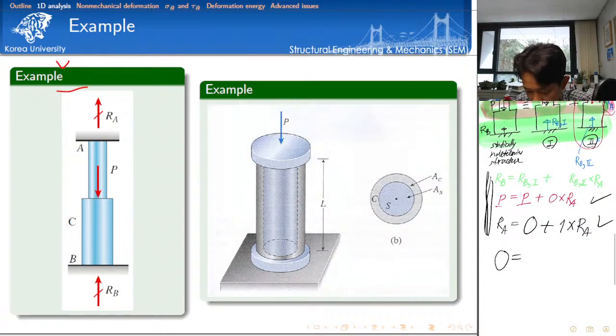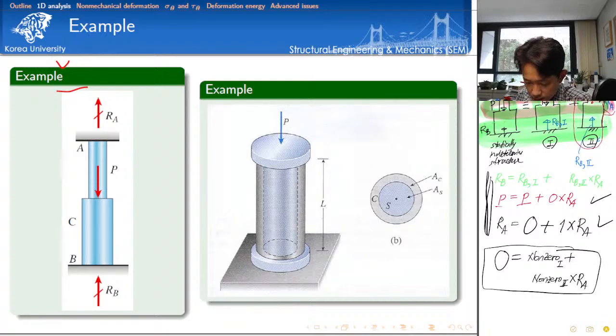And then I have non-zero, plus I also have non-zero system 1 plus the non-zero displacement, the point 2 times RA, isn't it? So which means here I have one equation. So we can calculate the displacement here, and then also I can calculate the displacement at this point. And because I have one unknown, I can determine the reaction very easily, isn't it?